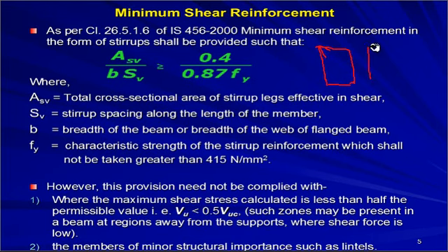So this is 2-leg stirrup. Then if you want to understand what is 3-leg stirrup, along with this master ring, one additional hook is provided, and that is called a 3-leg stirrup: 1, 2 and 3. For 4-leg stirrups, 2 rings are provided. This is the master ring, and this is the secondary ring. This is called a 4-leg stirrup.